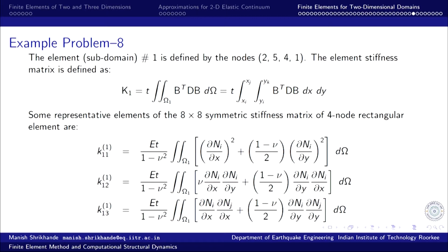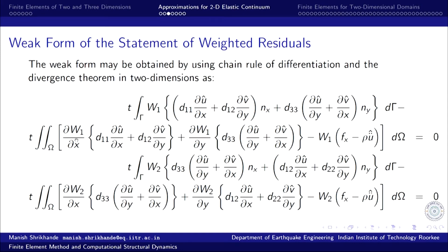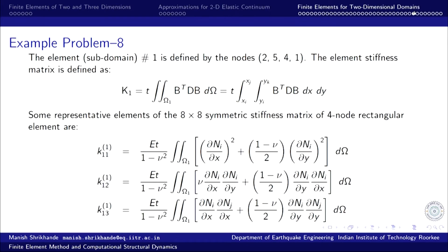If you recall, the strain displacement matrix involves the derivative of the interpolation function, and since our weighting function is del V, the derivative of the weighting function multiplies all of these terms. That is related to the strain displacement matrix, again for the Galerkin formulation. So, essentially it boils down to evaluation of an expression of this type, B transpose dB.